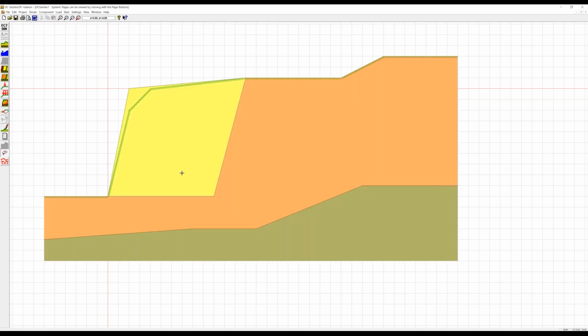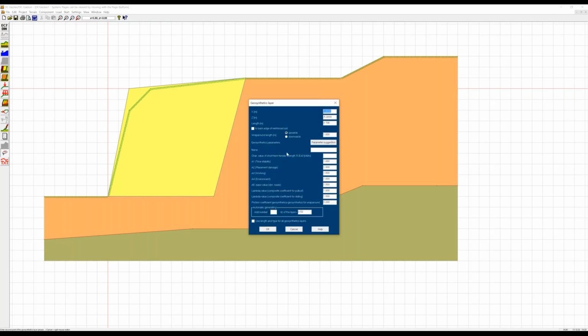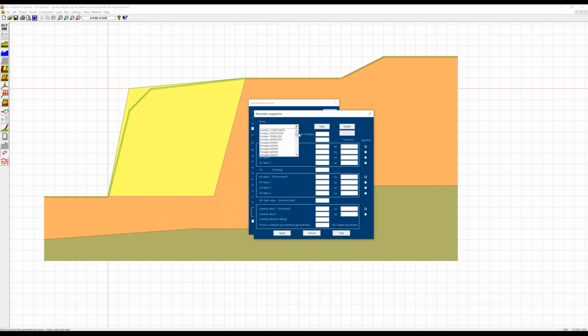Now this is our reinforced soil mass, and now we can define the geosynthetics levels or layers. So for example, we start here at the base of this shape, and we can define the type of geosynthetics with all the reduction factors, with the tensile strength of the geosynthetics. And again, we have parameter suggestions, and here we have many products predefined with all their values. This may be Comtrack, Incagrid, Fortrack, Geolon, Miragrid, Polyfield, Secogrid, Stavelinka, Tensor, and so on. You see quite a large number of different types that you can select here.